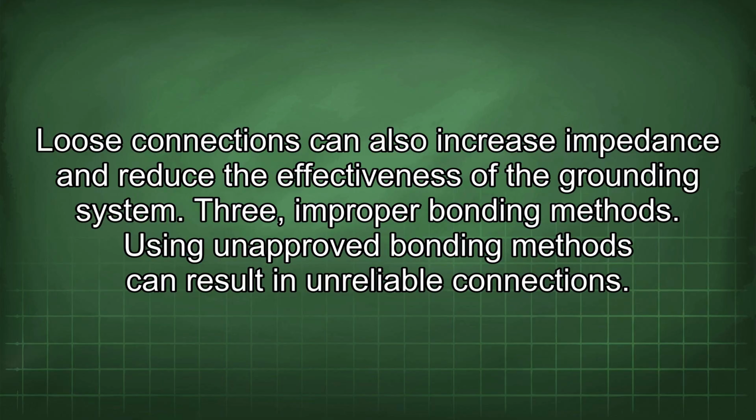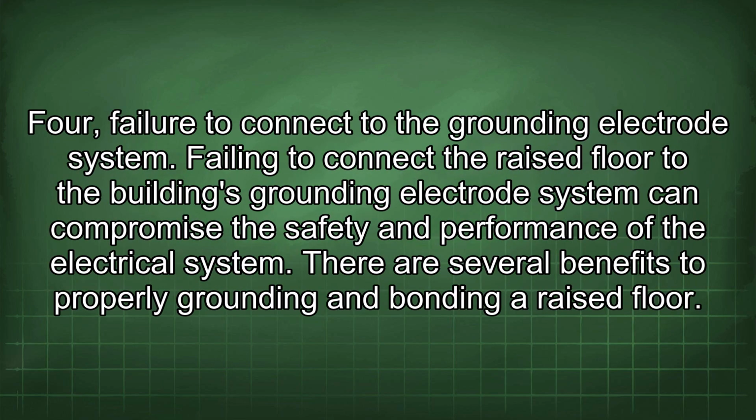3. Improper bonding methods. Using unapproved bonding methods can result in unreliable connections. 4. Failure to connect to the grounding electrode system. Failing to connect the raised floor to the building's grounding electrode system can compromise the safety and performance of the